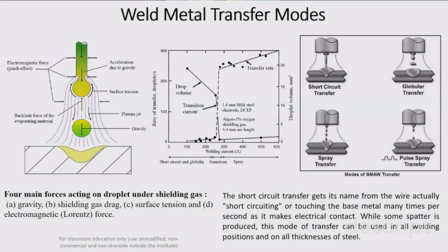This formation is a very important thing, and it will give you an idea about what the final microstructure will be when the metal is solidified. You know that the microstructure plays a very important role in the mechanical properties. In the welding process, the first thing is to obtain a defect-free joint, and the second thing is to obtain a favorable microstructure. Favorable microstructure means the microstructure should have refined grain in the welded section so that it will result in adequate strength and toughness.